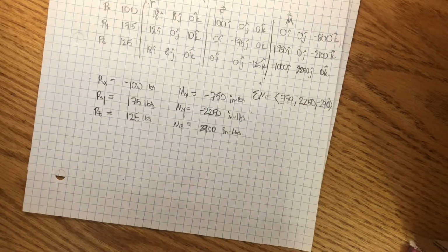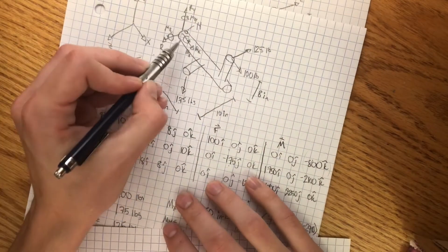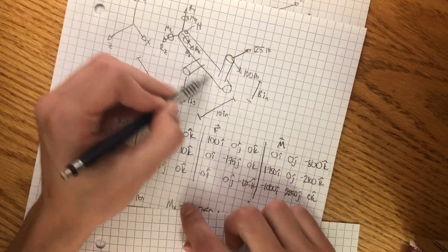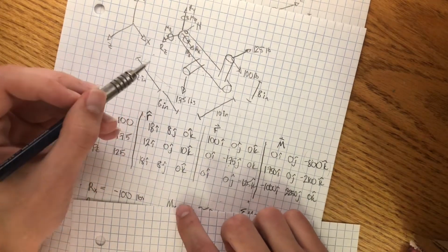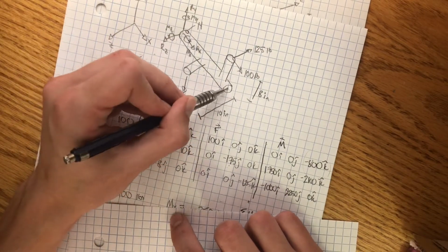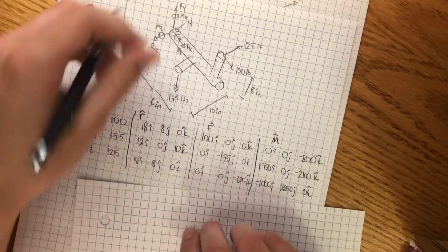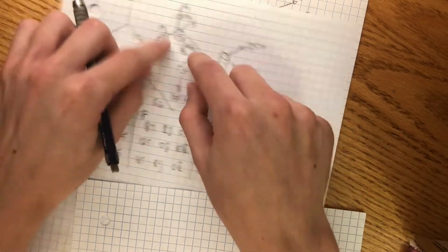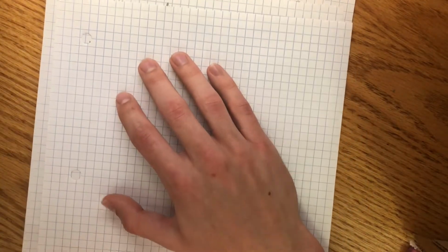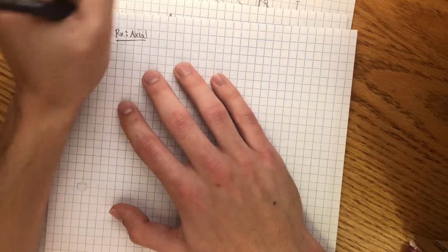So that's a negative 100 pound force, and as you can see here, Rx is going along the x-axis, which is actually along the longitudinal axis of this pipe right here. So that means that this is an axial force. It's going along the main axis of this tube. And that also means that it's going to create a tension or a compression, because shear forces want to snap stuff like that. This is just going to want to stretch or compress this object. So we look at it as an axial force. So we say Rx axial.